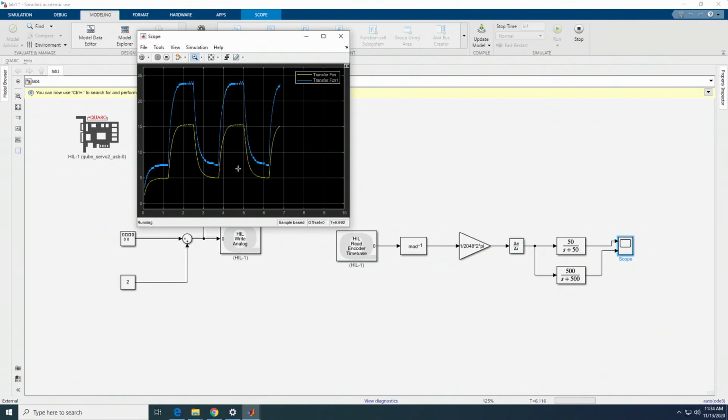As you can see, the response, which corresponds to the low-pass filter with a cutoff frequency of 500, is noisier. This is because we're getting rid of a smaller proportion of frequencies compared to the one that we're using on the top of the figure. So the one on top will attenuate any frequencies higher than 50 rad/s, and the one below will attenuate frequencies above 500, which are fewer.